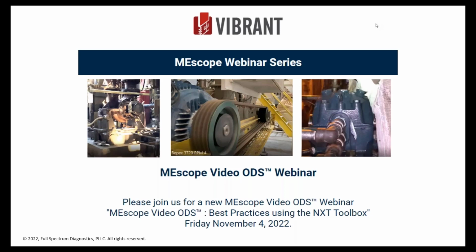So there's a couple different things we want to process. One is we just take our data normally, the discrete Fourier transform, and it includes phase in that piece of information that we're getting in the video clip. But we also want to look at the ODS-FRF, and the ODS is operating deflection shape. The FRF part of that shows us the phase. It calculates phase across the spectrum.